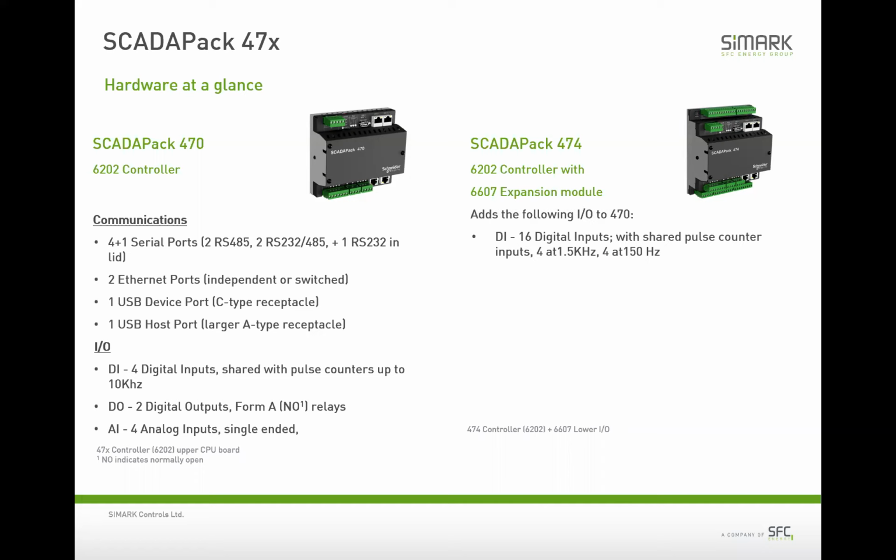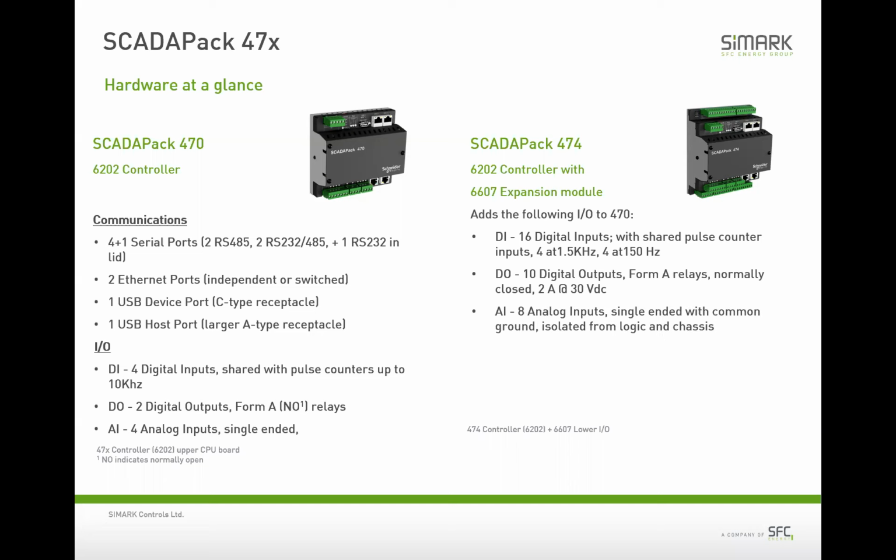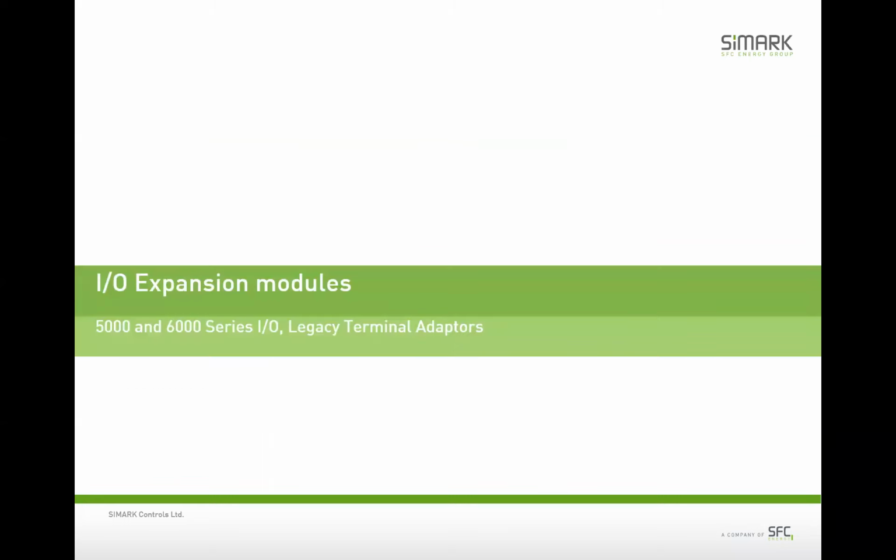That's adding in 16 digital inputs here, and you can see the extra counter support that's on there. We've got 10 digital outputs, 8 analog inputs, and the option to add in 2 analog outputs on that board then as well. So if you find that I/O is insufficient, then you do have the option of going to our range of expansion modules.